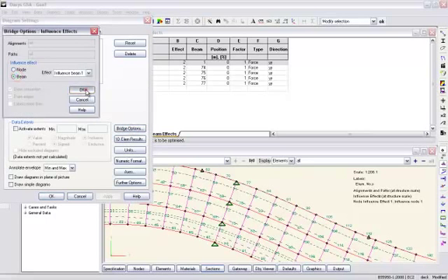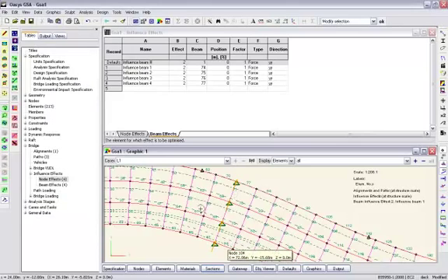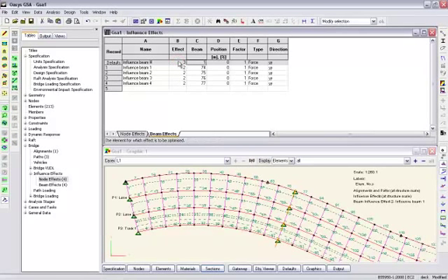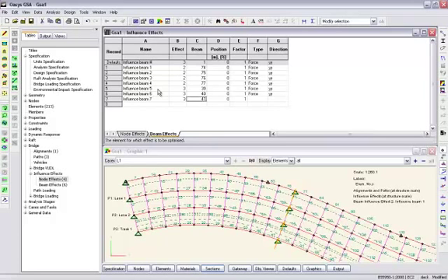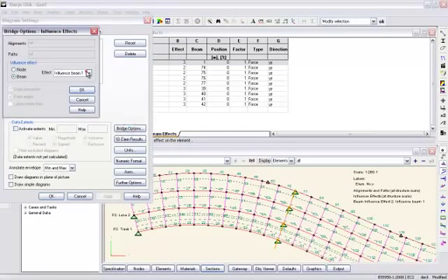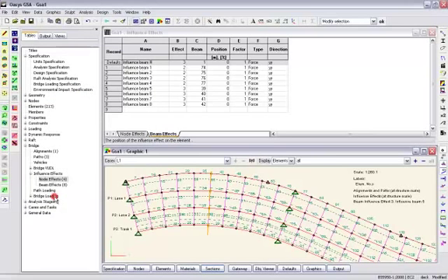Change the influence effects to the beam just to make sure they're there. Yep, you got that right. And I'll also take the mid-span moment on here as well, which will be this line. So I'll take 39 to 42. So I should change my grouping. 39, 40, 41. Let's just check that. Wonderful. So we have our influence points set up.